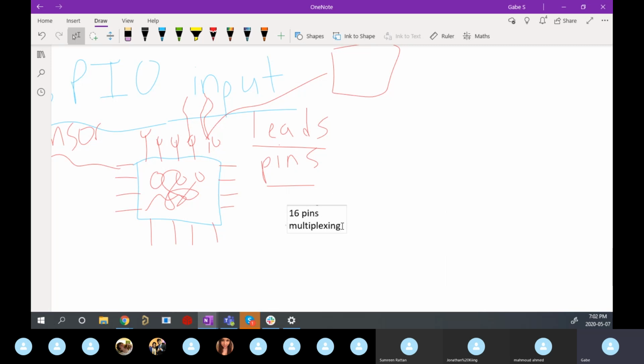On the TMS 570, which is the microcontroller used by Team Phantom, we have a thing called the pin mux. So multiplex is also shortened as mux. So this pin mux will allow you to select exactly what function you want on that pin, right? So once you know that, let's say I want my pin here, I have to configure it as a GPIO, right? I want to do digital stuff. I want to read from the world. I want it to be an input.